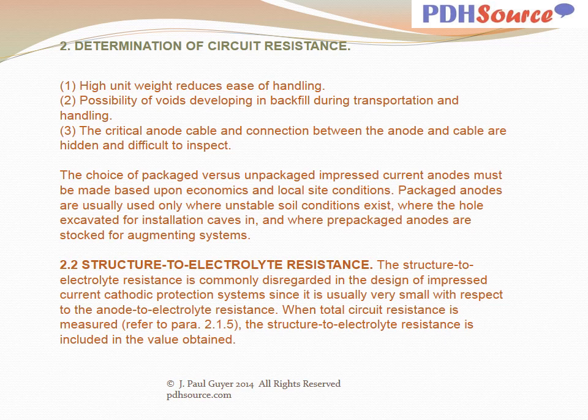The choice of packaged versus unpackaged impressed current anodes must be made based upon economics and local site conditions. Packaged anodes are usually used only where unstable soil conditions exist, where the hole excavated for installation caves in, and where prepackaged anodes are stocked for augmenting systems.